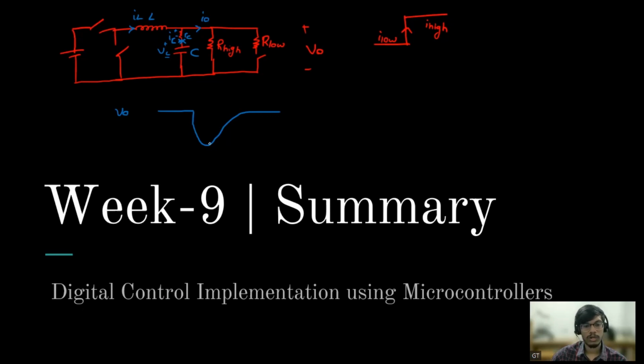And now the capacitor will recover. How will this recover? The inductor current is like this, and it will keep on charging to that new value. And so the V naught is something like this. At that instant, the capacitor has provided the current, so the output current has been reached, but we are running it in a closed loop. Now V naught has come down, and also the capacitor has to be charged because the voltage has come down. So in the meantime, the closed loop will ensure this.